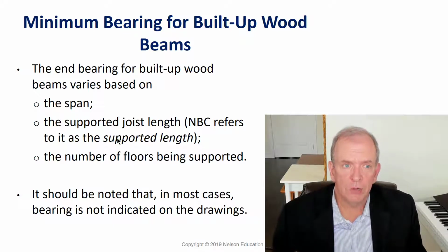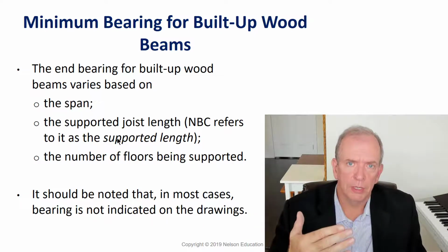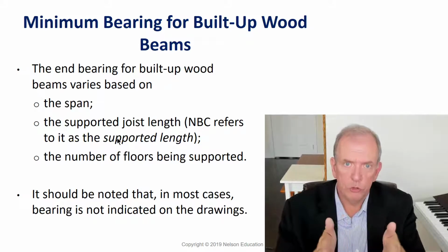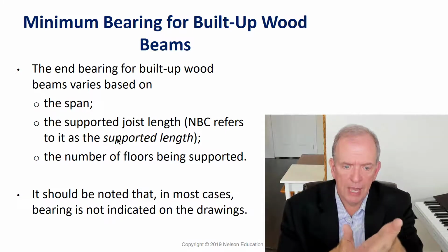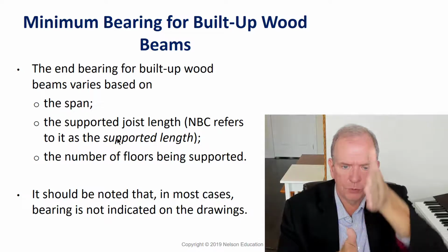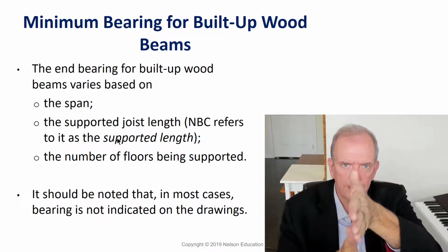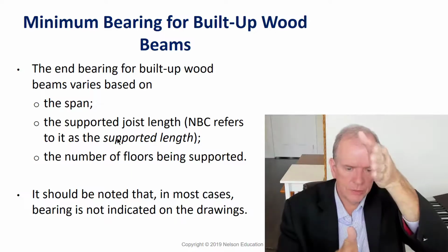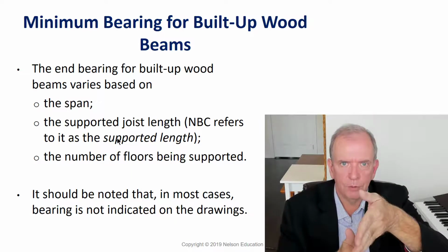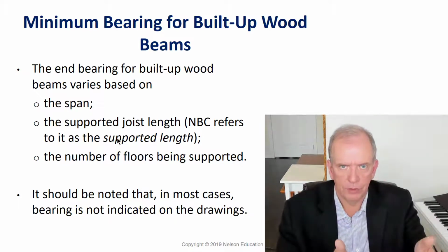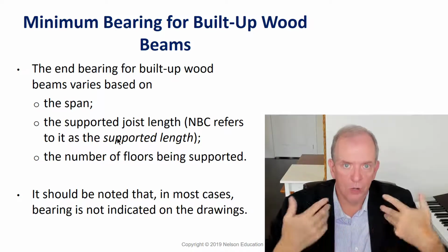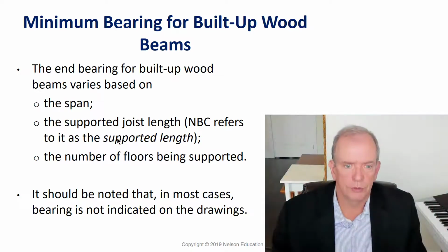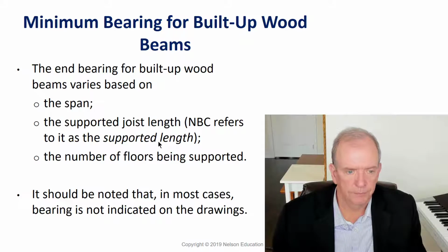Then the other thing that has to go into consideration is how many floors it is supporting. Is it a 2-story house? Is it a 3-story house? So if it's in the basement, then that beam is carrying the weight of the first floor, and maybe there's a load-bearing wall on top of that. So now that beam is also carrying the weight from the second floor and the first floor. So again, it's going to have to be designed to be strong enough to carry the weight of both floors, and so on.